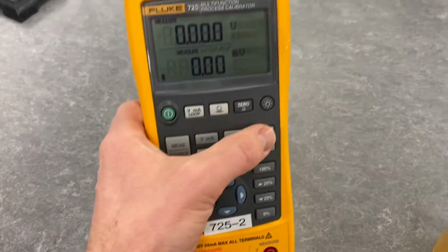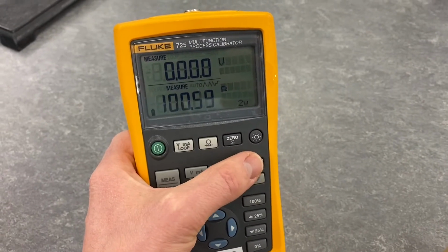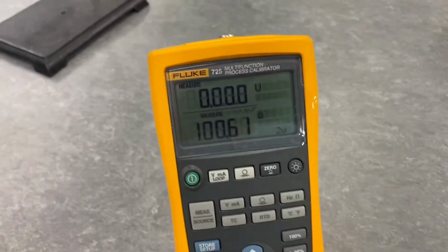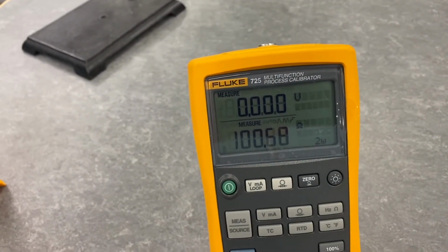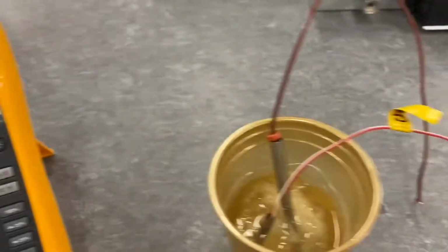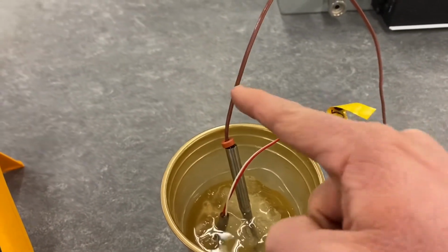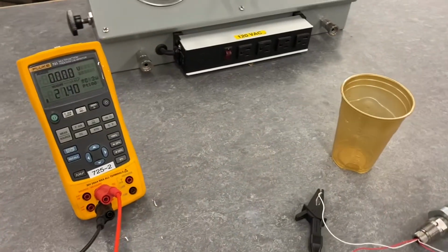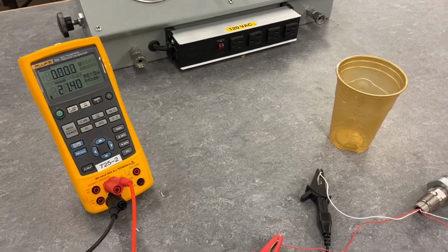If I toggle back here, press the resistance button, it needs to be set for 2-wire, and there you can see we're back close to 100 ohms. And if I just agitate this, it should even drop down lower, closer to 100 ohms. So there, RTD measures changes its resistance. Thermocouple changes the voltage that it generates with temperature. All right, so in the last part of this lab, what we're going to be doing is